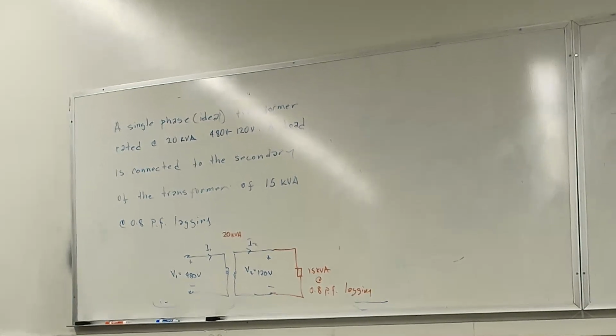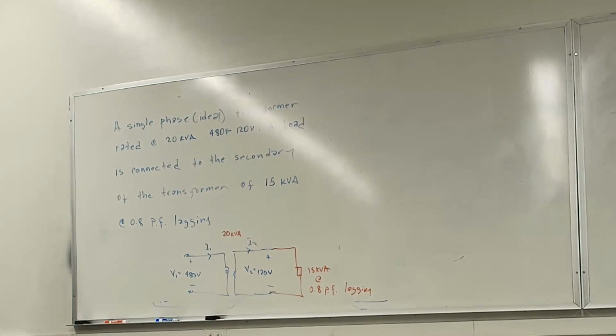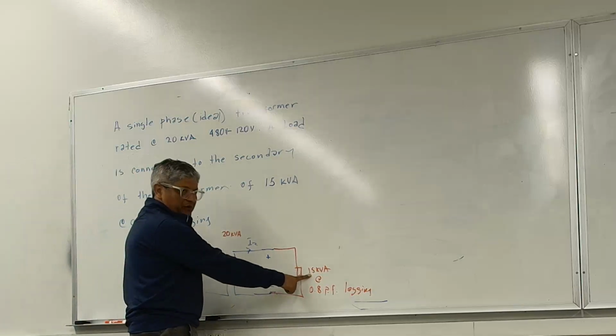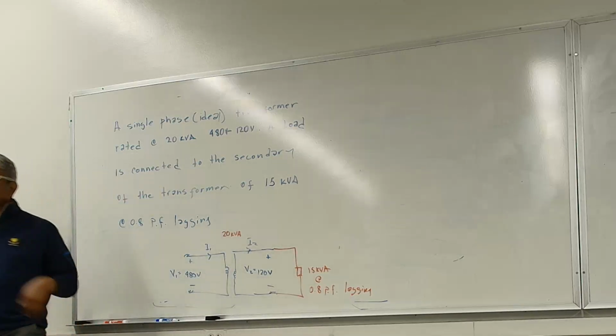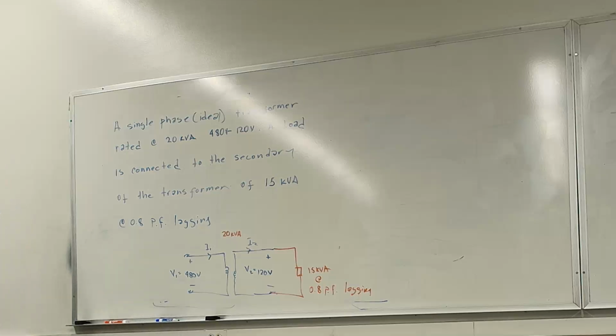They can be pulling less, or they can be pulling a little more load throughout the day. Now, less should not be a problem. You should be okay. Your transformer should be able to run without any issues. The problem becomes when the load increases above the rating of the transformer. Can you do that? The answer is yes. Companies do it every day.